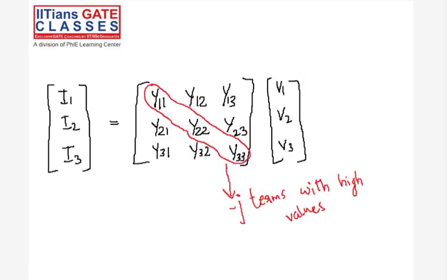So when we are looking at Y12, we are talking about the element between node 1 and node 2, which is usually a combination of a transformer, a transmission line, and a transformer, or sometimes just a transmission line. Unless we are having an HVDC line, or we are actually adding physical capacitance in the form of series compensation, it is by general nature inductive. So does that make sense now for the people who it didn't make sense earlier?